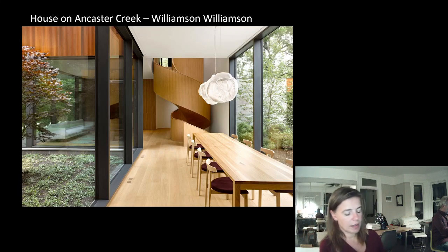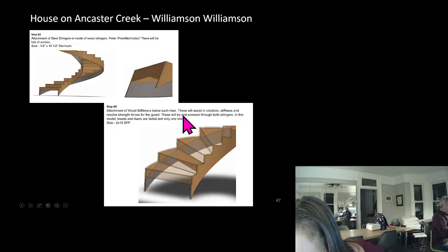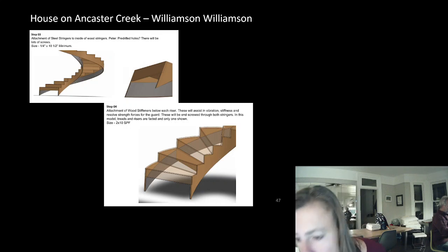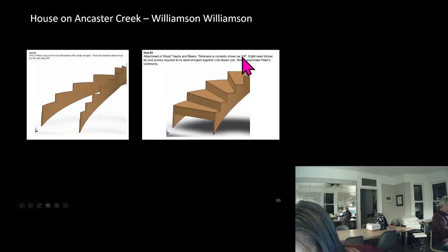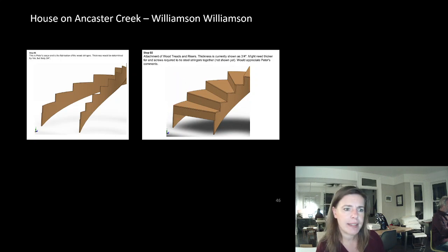We had 3 divided by 8 times 4 plus 0.25 plus 3/4 of an inch, so 0.75. So the whole thickness was only 2.5 inches, and that was only down here where the stair was. Up here, we had less than 2 inches at the guard thickness.